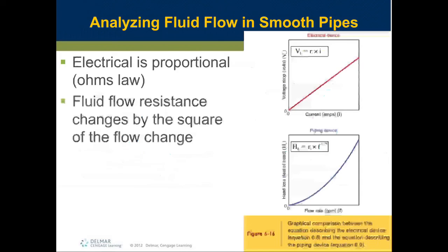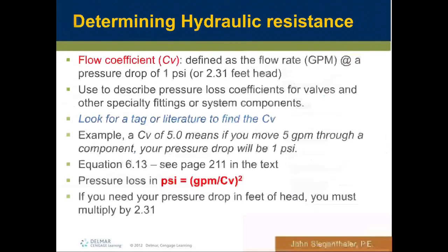It was a straight 1-to-1 ratio. When we look at the resistance of a system, it's an actual squared relationship, so it's an actual curvature. We'll look at this in a little more detail, as it relates to how we recognize, if we're going to double flows or quadruple flows, what happens to its resistance, and is it realistically even achievable?